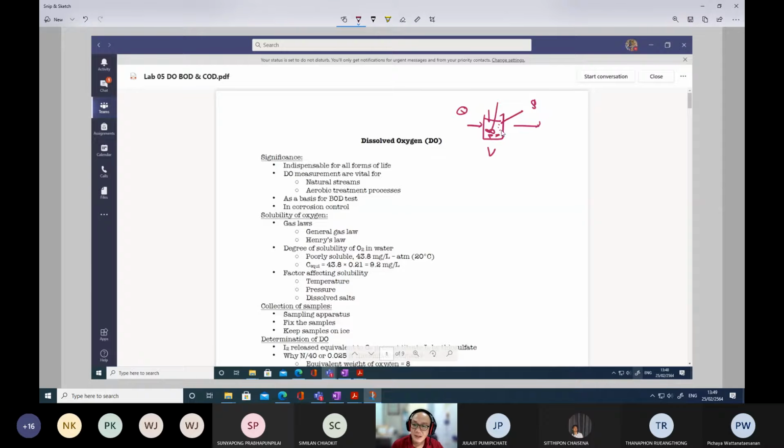So we provide the oxygens. In this reactor, the organic substance which we measure in terms of the BOD will react with the oxygens, through the microorganisms. The microorganisms can utilize and degrade it, and the end products are carbon dioxide and water molecules. The oxygens are consumed as we provide a significant amount of oxygens, which the microorganisms utilize.